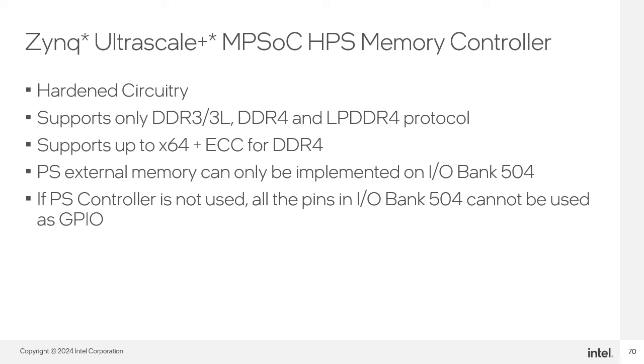The Zynq MPSoC processor system hard memory controller uses hardened circuitry. It supports only DDR3, DDR4, and LPDDR4 protocols. The processor system external memory can only be implemented on its dedicated I/O bank, and you cannot use this bank for any other purpose when the PS memory controller is not used.